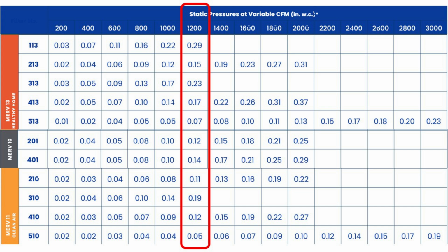Likewise with the filter, when people come in, they'll say the term high efficiency. They might give me a size. Rarely are they asking about static pressure drop. They say I want a 3-ton, a filter big enough for a 3-ton. They don't talk static pressures. But here's a lot of examples.